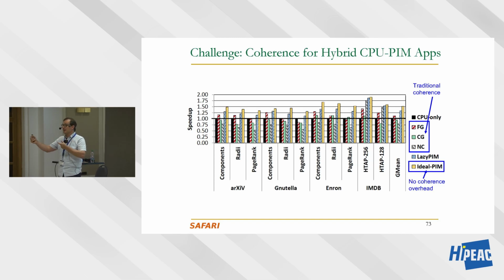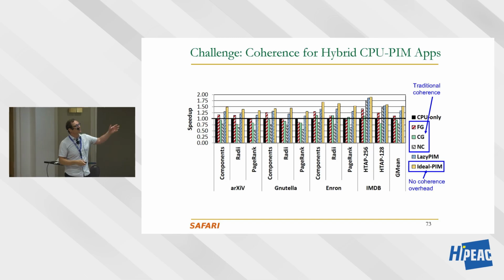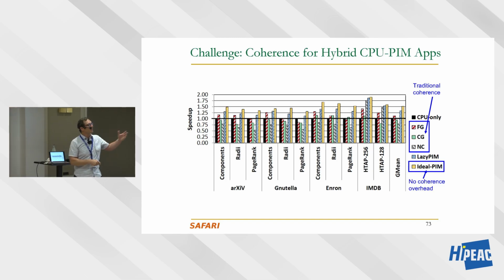And for that, if for example you ship some code far away to the near memory processor, if the near memory processor now needs to go back to a directory to check whether it can actually access that code and update that data element, that's very bad, because now you're causing a lot of coherence communication back and forth, and we wanted to eliminate all communication to begin with. So you need to handle coherence in a careful way, and a lot of our papers cover that.